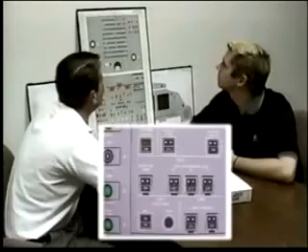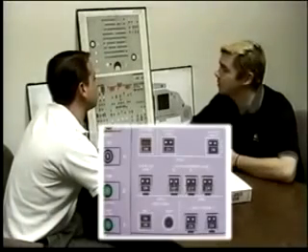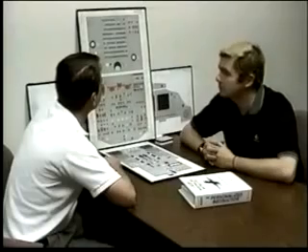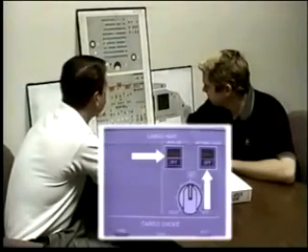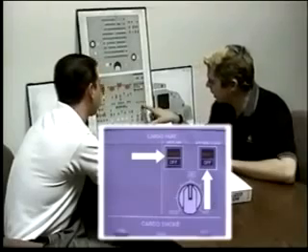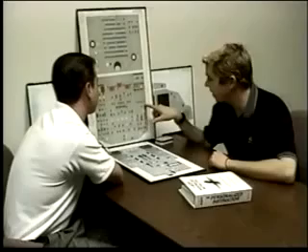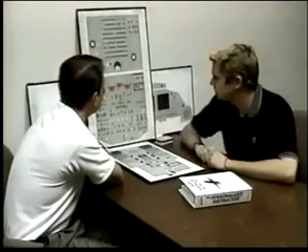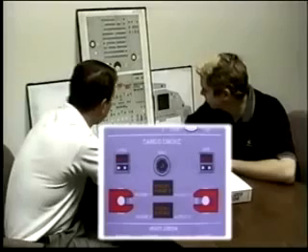Overhead maintenance panel, anything that you're concerned with on that panel? Only if I see a light up there. If I see a light, I'm going to be calling maintenance, but other than that, no. Cargo heat. You have a hot air and an aft isolation valve. Pretty simple. Hot air means it's too hot. It's an over temperature. Aft isolation valve disagreement. Cargo smoke. On the 320, you have 2 bottles.